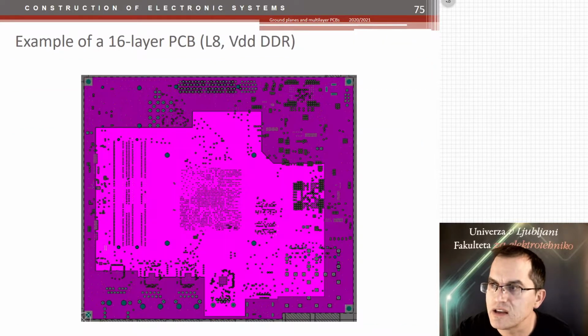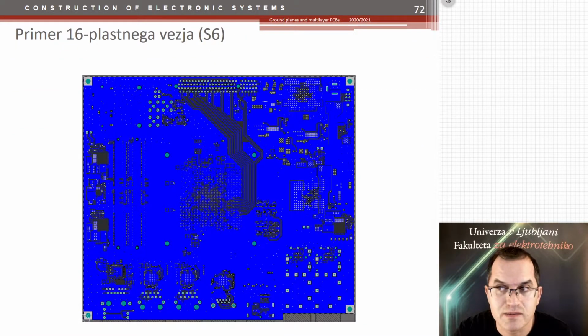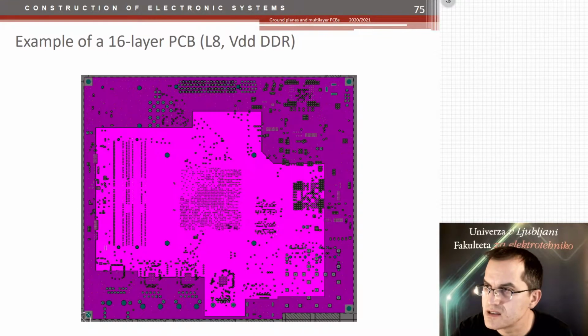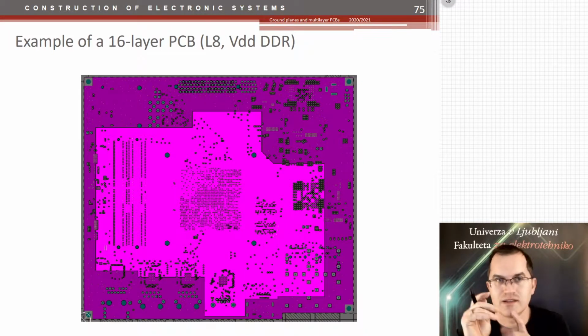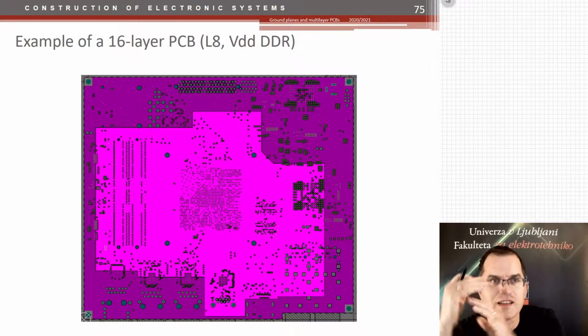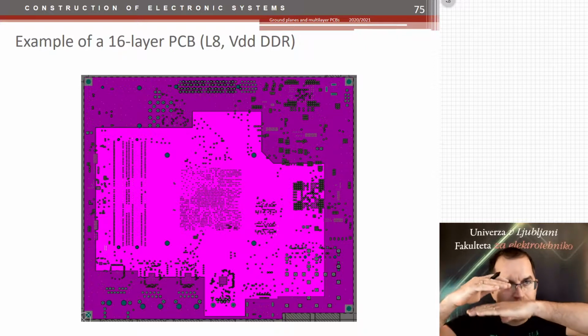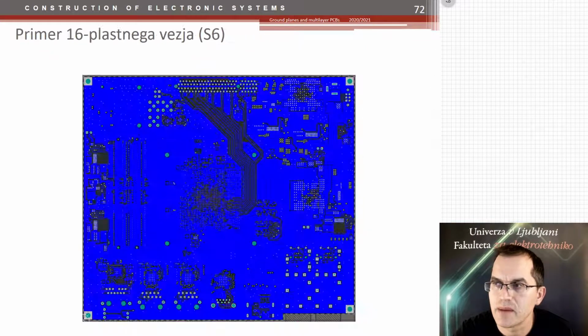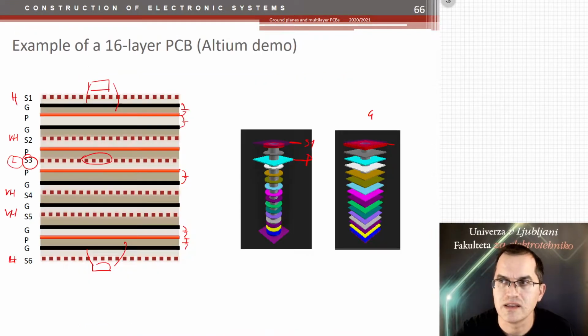And the highest frequency power is actually not taken from these capacitors. It is actually taken from the ground planes. And that would then make the capacitance the best there is. It's taken, sorry, it's not taken from the planes, it's taken from the space between the planes, between the ground and power planes, which are kept closer in this stack. Here, here, and here.